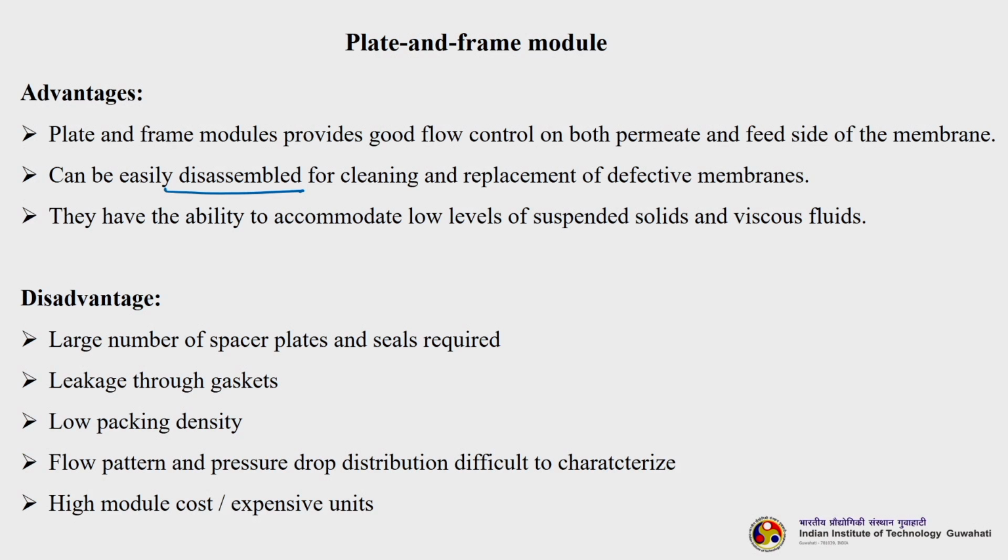So, you have to take sufficient care so that there is no leakage, because pressure also gets developed inside the membrane module. Leakage happens, and the packing density is very low compared to other types of modules. The flow pattern and pressure drop distribution are very difficult to characterize, and the cost of the module is high.